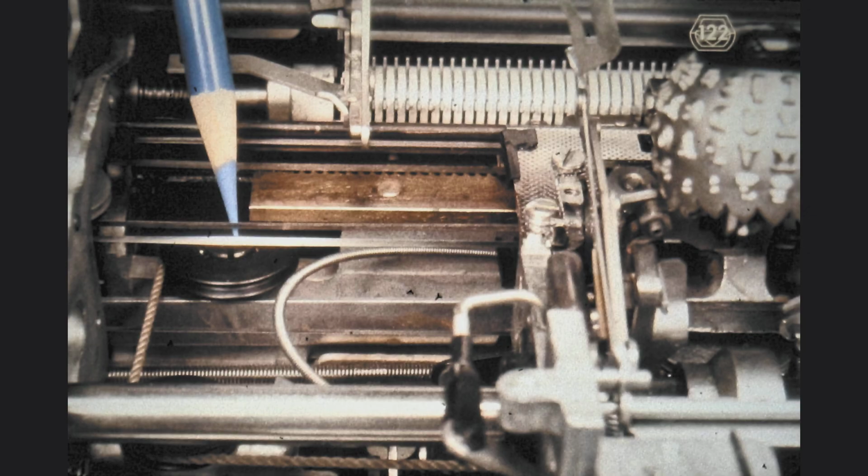This is a picture of the rotate tape already installed. The objective here is to show you which way the rotate tape was twisted prior to being inserted into the opening of the rocker shaft. Notice that the tape was twisted on the right end, top towards the front, so that during printing, when the tape has to twist with the rocker movement towards the platen, the tendency is to untwist the tape as the element moves towards the platen.